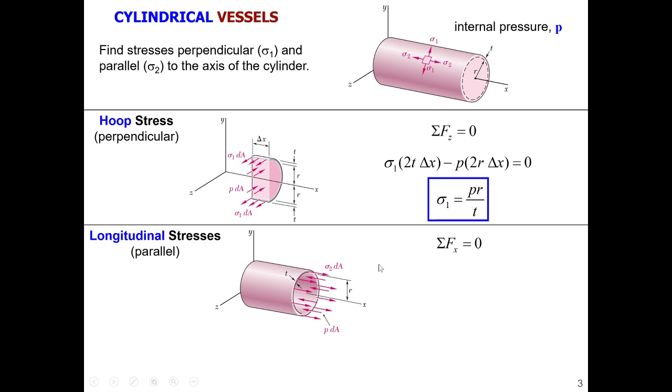Okay, so obviously that part will be okay. So we just have the area of the thickness here, right? So the 2πRT, and now the rest of that is equilibrated against the fluid pressure in this direction and the area of that remaining part here, right? So that's where the fluid pushes back, πR squared. Okay, so that's the area that produces force, and the same here. So stress multiplied by the corresponding area, and so we again have the force.